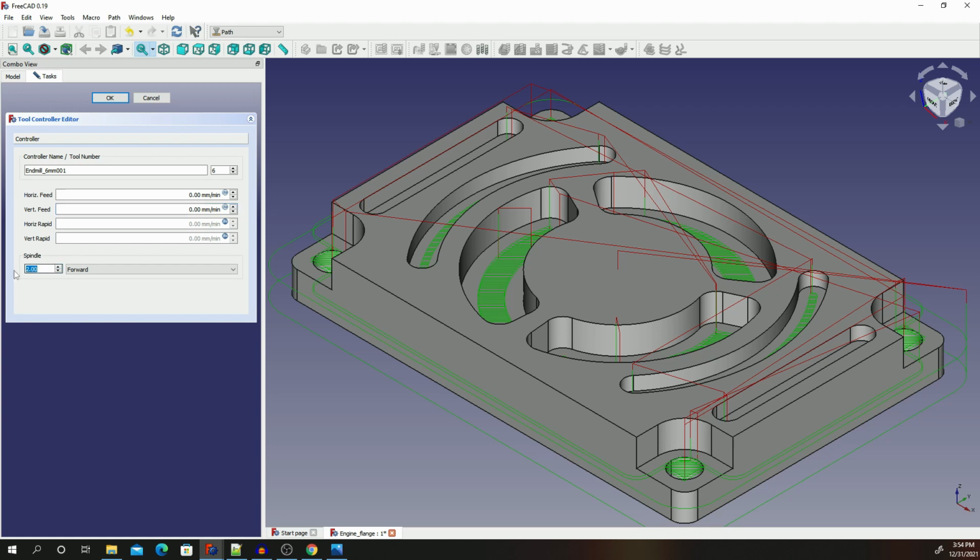Yeah. In most cases, these cutting tools like facing, depending on your tool, you're going to use spindle speeds of sometimes 500 and above, right? So you always define your spindle speeds in here, your feed rate, and both horizontal and vertical feed rates. And then to increase the speed of machining, you can also determine the rapid speeds, but just be cautious, right? By default in FreeCAD, just make sure you don't edit these to avoid any crashes. You can always adjust your rapid speeds, but I would suggest leave this at its default.